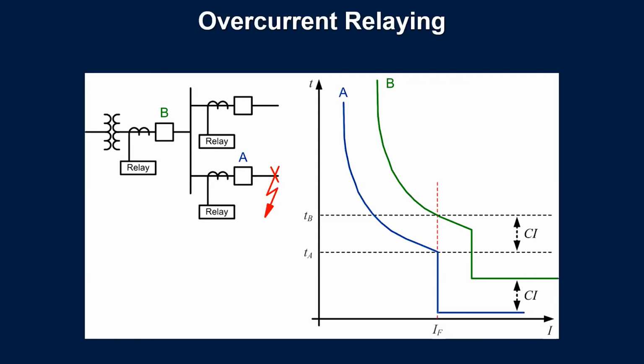I'm not sure if everyone's familiar with typical protection here or not, but if you are, then you'll recognize this diagram. Pretty typically, you might have a source feeding my transformer. The secondary of the transformer comes into my switchgear through a main breaker or an incomer, depending on terminology you like to use. Coming off of that, the bus inside the switchgear will have several cubicles for feeders. And if there's a fault, not necessarily an arcing fault, but any fault on my power system, I'm relying on relays that are measuring the current on the power system to identify the fault and command a breaker to trip, and hopefully the right breaker.